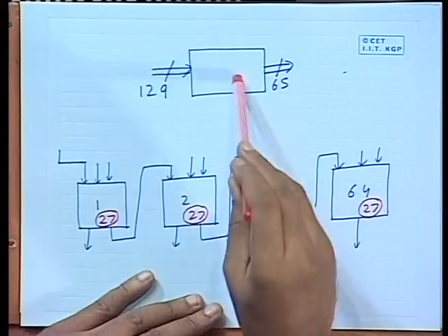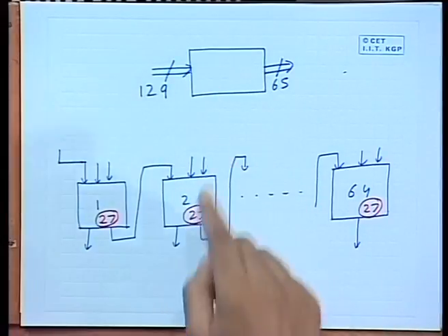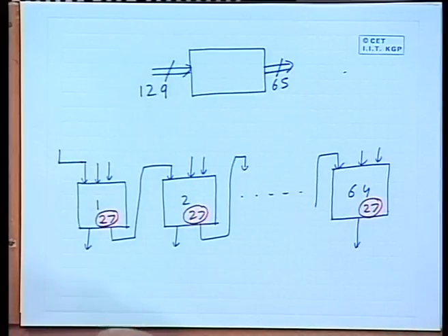So, now let us compare these two alternatives. What is the complexity of test generation? See, the first alternative, the functional test pattern generator: if you treat the whole thing as a black box, then nothing will give you confidence, unless you apply all possible inputs and see the outputs, because you do not know which subset of inputs to apply in order to test it.